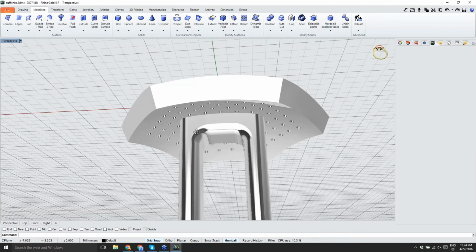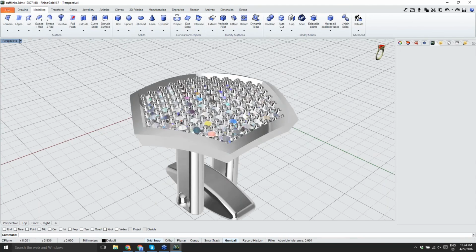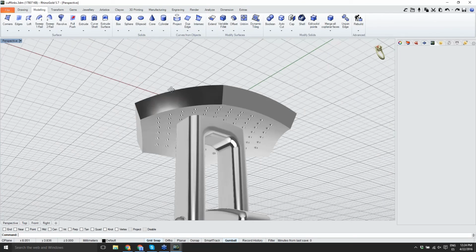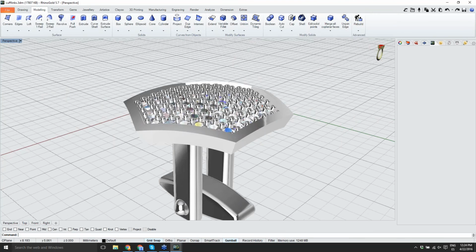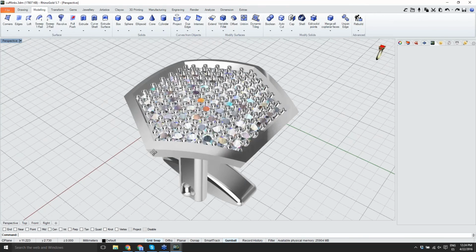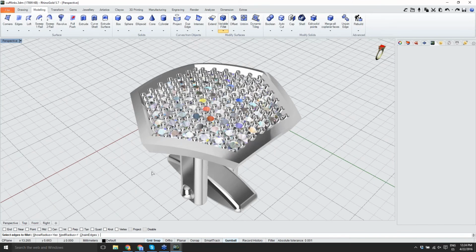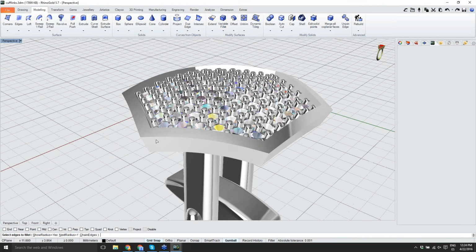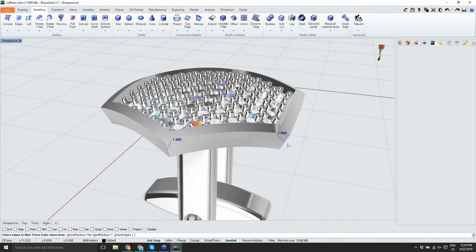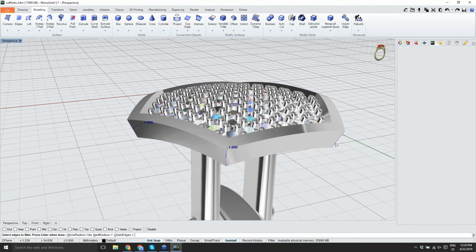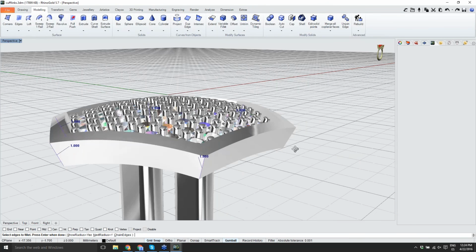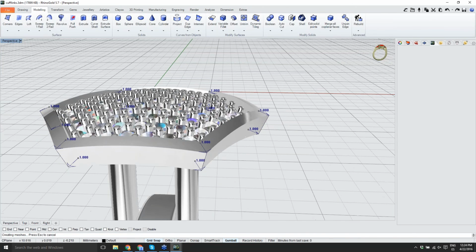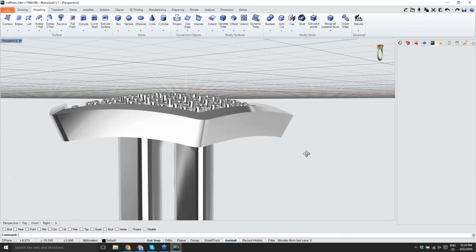So we have been checking several tools, the Pavé, the prongs, the shell curve. So this is the result. I can, of course, in the end, just for instance, with the variable fillet tool, break these sharp corners, so I can easily select and say, okay, I want to apply a fillet angle with a 1 millimeter radius. So I can just select the edges I want to fillet, and I just press enter. So as you can see, this will be the result.